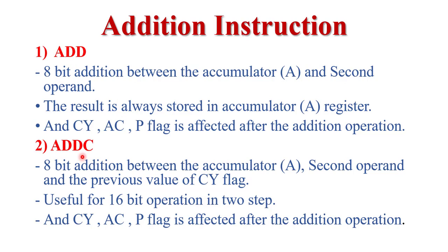Next is ADDC, the addition with carry instruction. This is the same as the addition instruction, only the carry is included. In the case of ADDC, 8-bit addition between the accumulator content, the second operand, and the previous value of the carry flag is performed. This type of instruction is useful for 16-bit operations in 2 steps. And after the addition operation, the carry flag, auxiliary carry flag, and parity flag are affected.